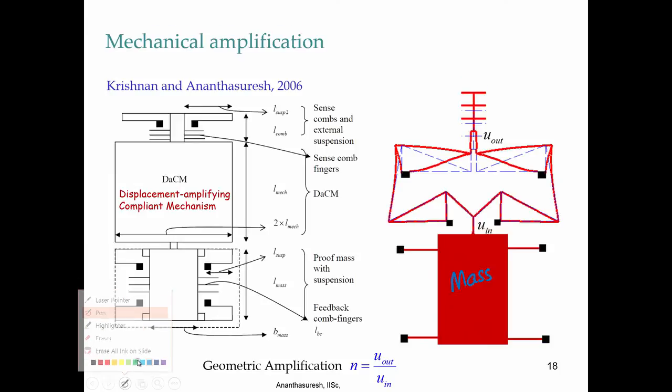It is going to deform, and there are these beams which we call a suspension. This is the beam suspension. It will move and you can measure the displacement electrostatically, but what we say here is that instead of doing that electrostatic sensing over here of the movement of the mass in that direction, we amplify it here. What was here has now moved to here. So, it is a lot of displacement from here to here, where input has not moved much at all.